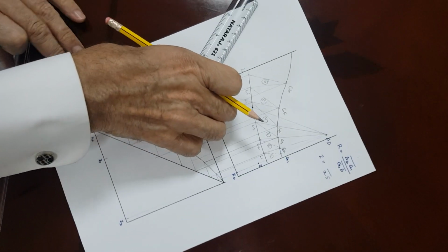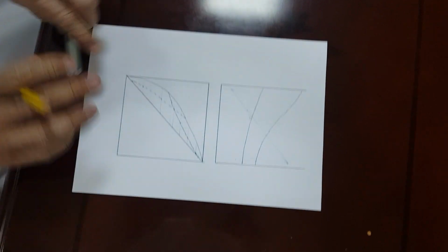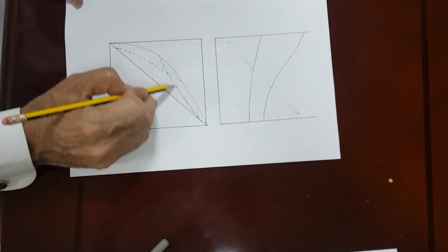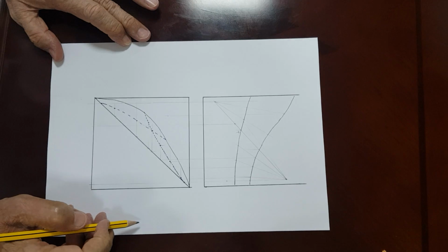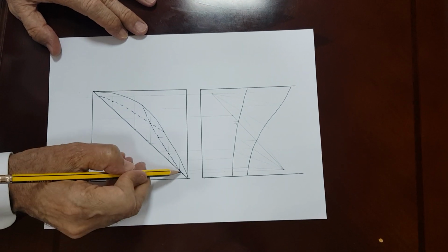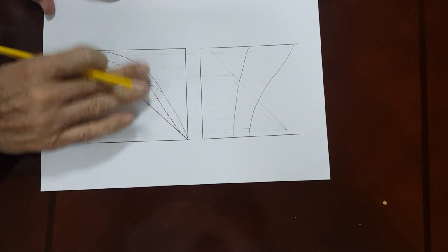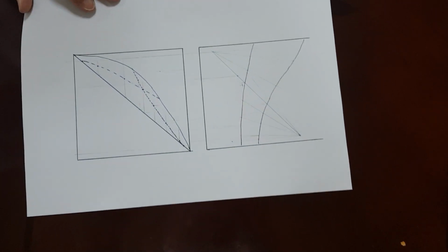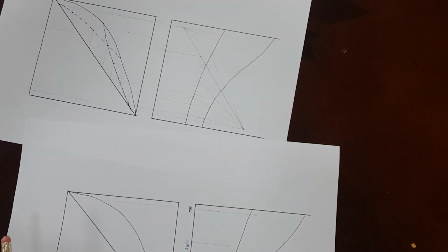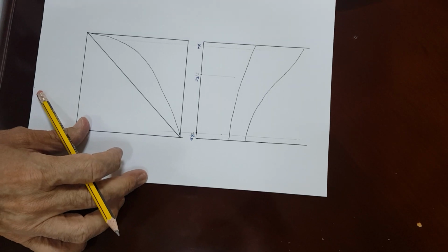So this is the first method. The second method is to find the nonlinear operating lines for the enriching and the stripping sections. And then you can use that to draw the steps using just the Y versus X diagram without using the enthalpy. And you should end up with the same result as the previous method. And to do this, we do the same thing.